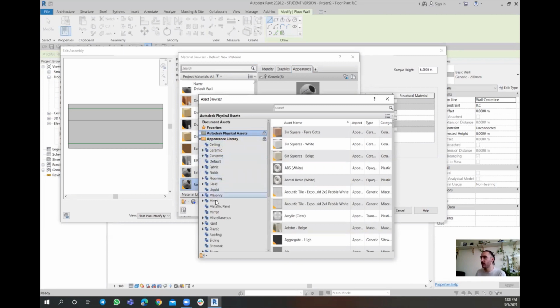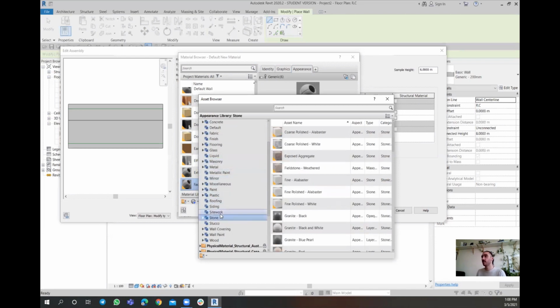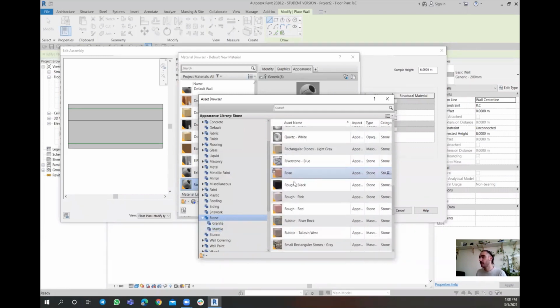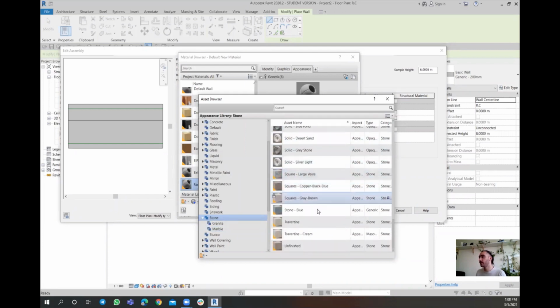You can see different styles and materials, depending on what you're searching for. I'm searching for tile, and since this is a facade wall, I wish to have a stone tile. That's why I'm sticking with stone. Even for stone, you can open the drop-down and choose different styles of stone. From here, I scroll down till I end up with Travertine Cream.